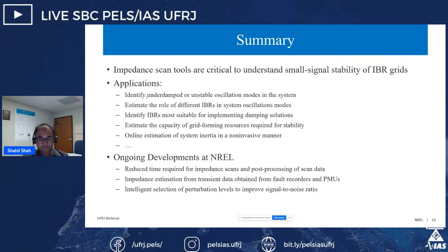The third is accuracy, because you can do a very nice impedance scan for small simulation models, which are very stable. There is no noise. But when you get PSCAD models from vendors, which are real code models, use real software codes, there's going to be a lot of jitter. If you see a big power system model in PSCAD, even in steady state, you will not have really flat voltages and currents.